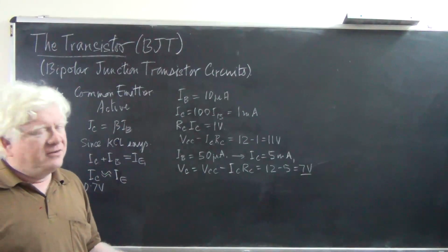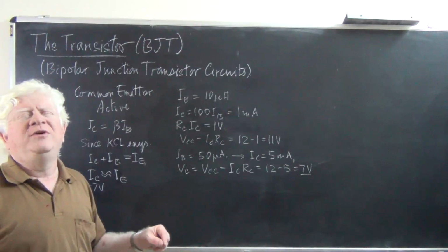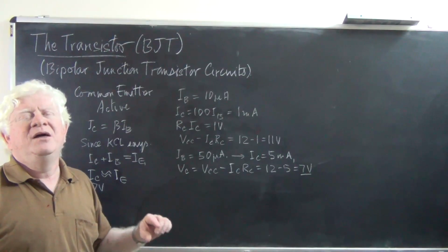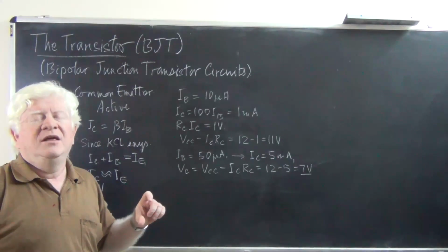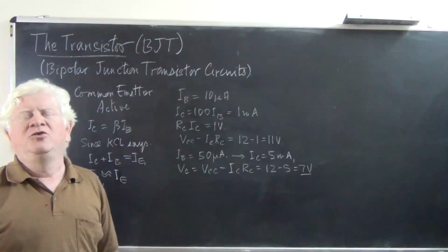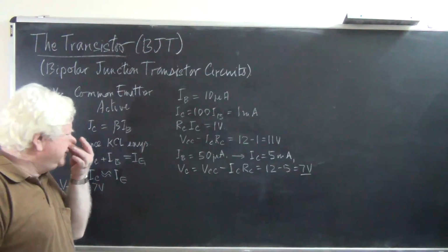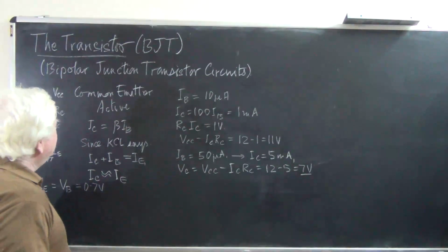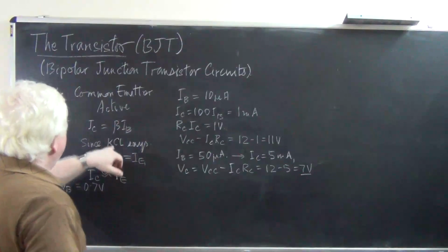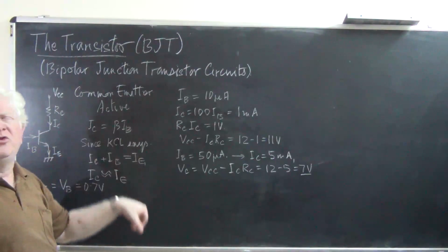It comes to a low value called VCE sat, which is the minimum or the saturation voltage that lies between collector and emitter. That's around 0.2 volts. So let's see what base current you need to just enter saturation. In this case, you have 12 volts of the supply to bring down to 0.2.